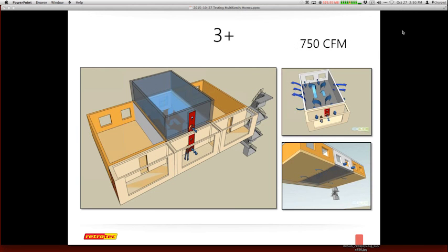Which I have to do now, actually, if I want to isolate what's happening above and below in terms of my leakage. Some of the places I tested in New York, I found that the unit to unit was actually pretty fine. It was their chaseways that were their greatest issues, with a lot of air movement through their mechanical systems, from behind their plumbing chases or their plumbing walls, and others that just allowed air to move freely through all the floors.